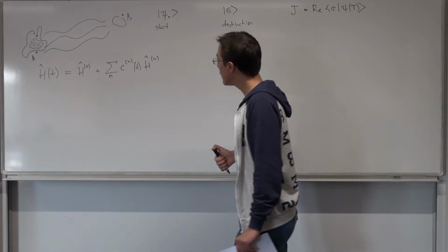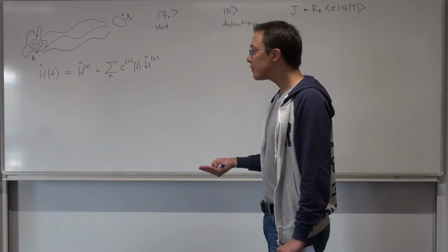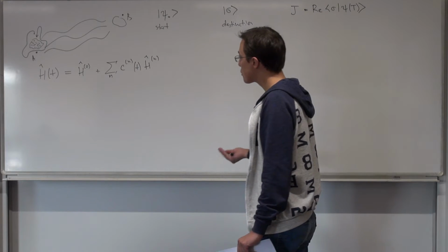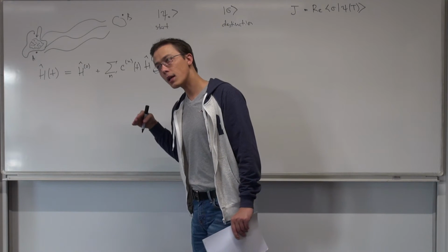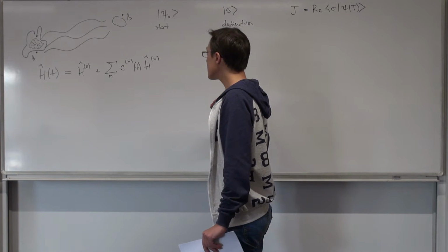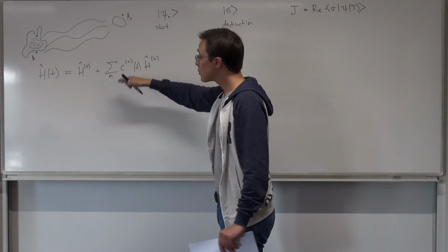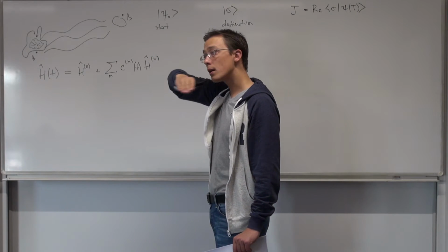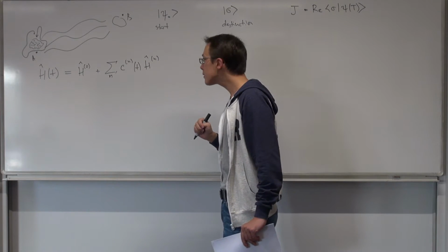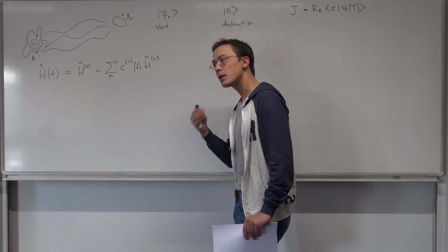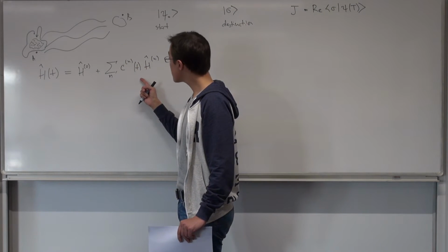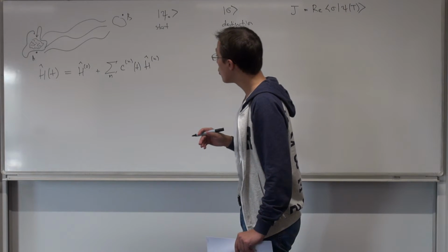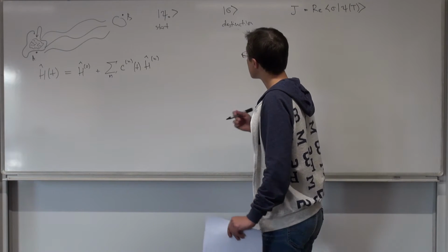The duty cycles of amplifiers are finite, and so the total integrated amplitude of these things can be capped. We would want, in some cases, for them to decay smoothly and rise smoothly at the beginning and end of the control sequence, so we don't have any jitter. And so there will be various constraints placed on that, which we do need to account for.